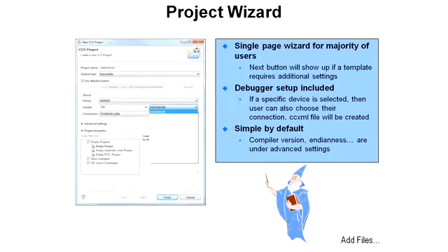So we make sure that the code that we're writing complies with the size restrictions that we have for the part. We can specify what the connection here is to our emulator. In this case, we could have said it's the simulator, but in this case, it's the USB connection to our LaunchPad. Then down where it says project templates, and the empty projects, you can pick a regular C empty project, an assembly only. There's other examples as well.